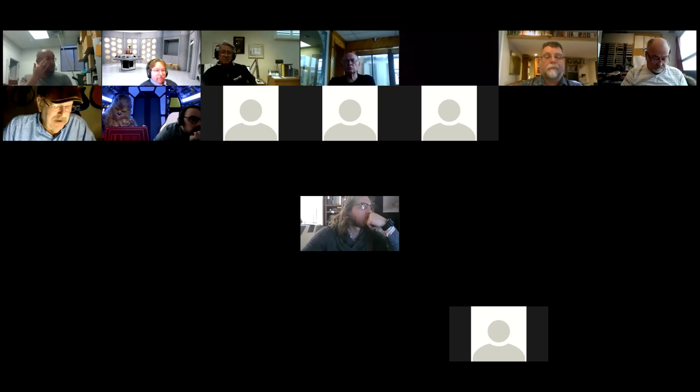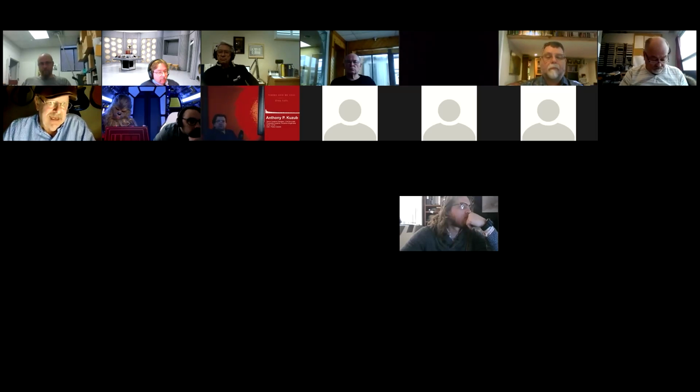Anthony, I don't know what the answer is. You have to train your personnel. You have to keep an eye on all the processing there. You are going to get audio in from other sources that has already been badly compressed. I showed you that last time. Some processors have what they call declipping, and they try to correct for some of that. So there you're going to have to spend money and buy a really good processor, and that's going to be top of the line Omnia, top of the line Voices, or something like that, that specifically has declipping, decompression, and correction for things like that.